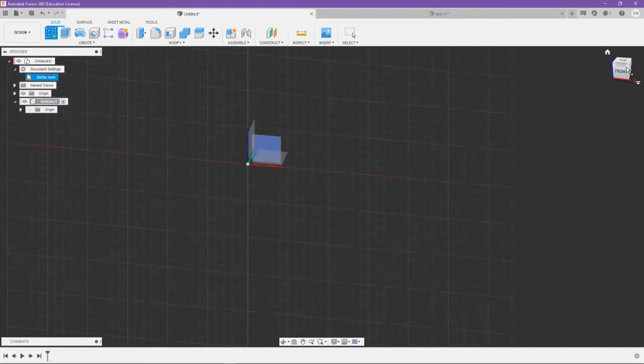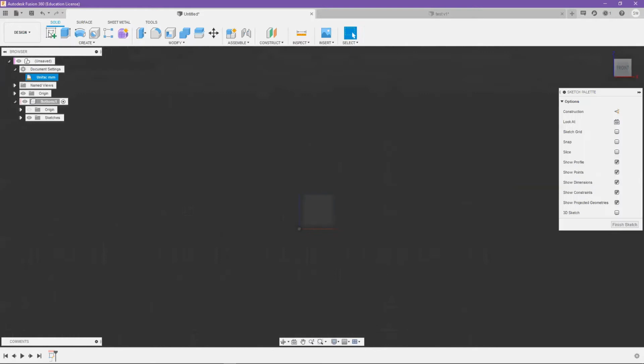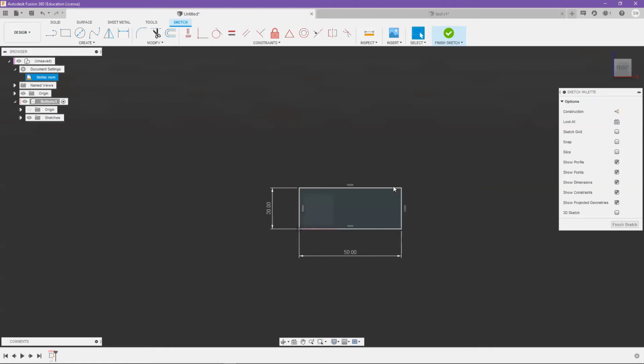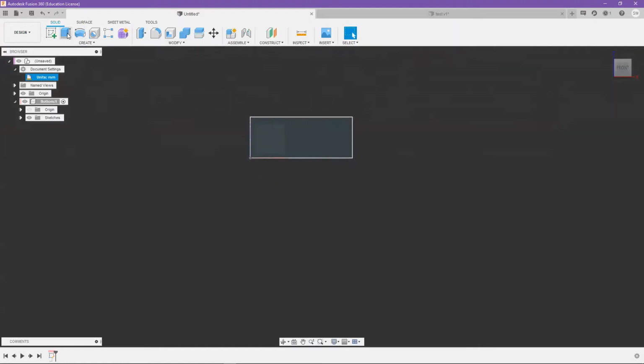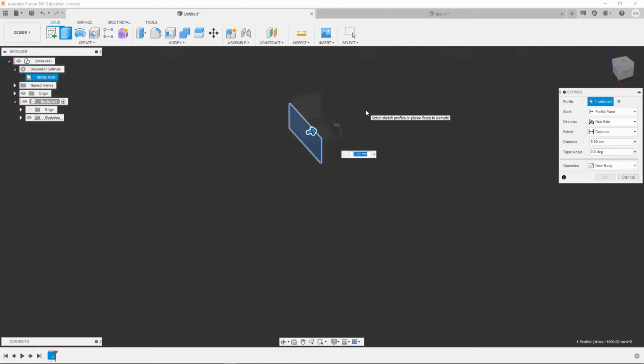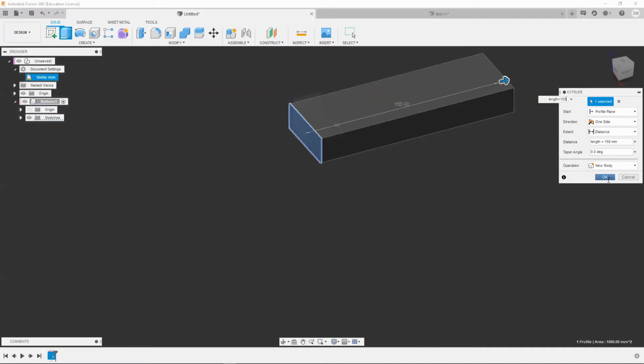Let's create our sketch again in the front face. Put the dimension, so I said half height 20. Let's put the depth to, instead of a relationship, we're just going to put a number here, say 50 millimeters. Okay, that's cool. Finish our sketch, go into extrude, click on that, and now add the length of our box. Let's say 150. I don't really know how long my pencils are, but 150 seems to be a good number.